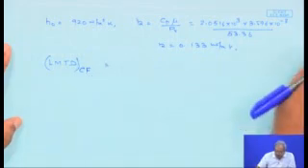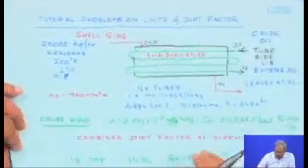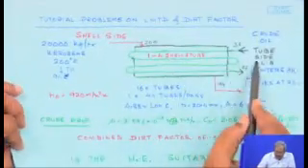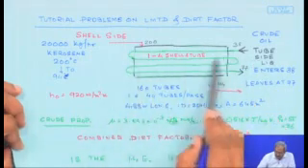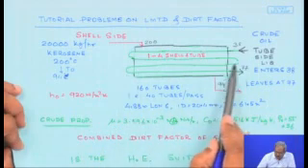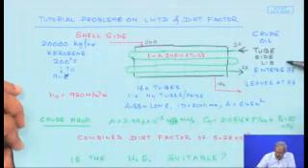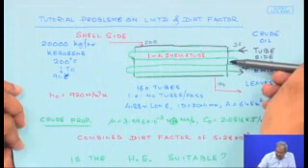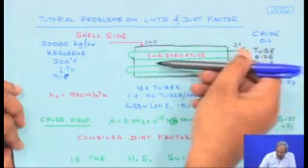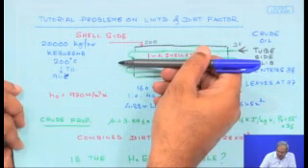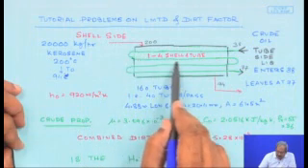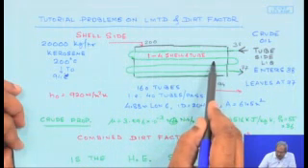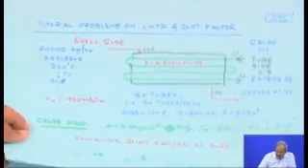So, if we go back to this figure once again, based on counter flow, it is as if the whole fluid is moving in this direction. Instead of these 4 passes, I just have one pass where the crude oil enters from this side at 38 and leaves on the other side at 77, and the shell side fluid comes in at 200 and flows counter to the crude oil and leaves at 94.